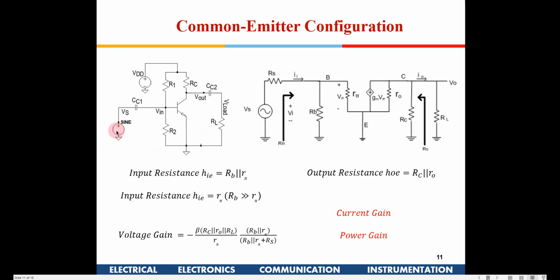So see, if you see the input side, the voltage is less, current is less. Output side, the voltage is high, the current is high. So obviously the power, whatever VDD we are connecting here, the power is being consumed from there. So there is an amplification of the power. Power cannot be destroyed or created, right? If the load is taking more power than what the source is providing, then somebody has to give that additional power, and that is given by this VDD which is connected here.